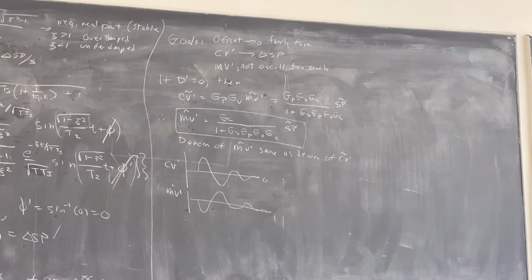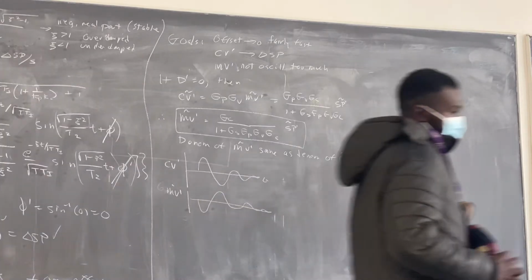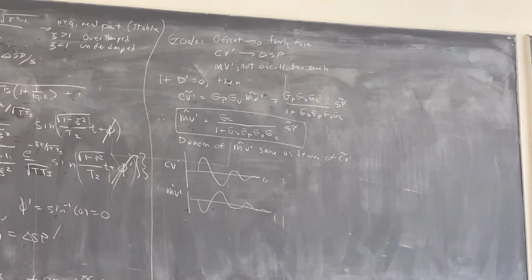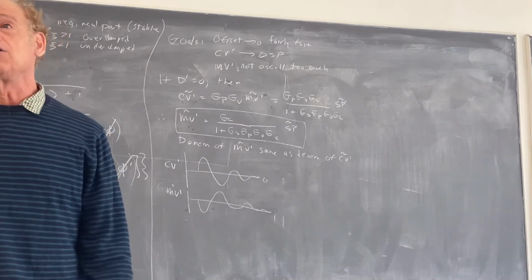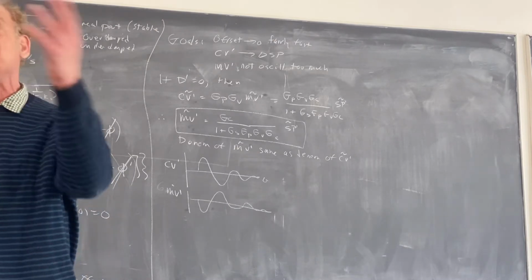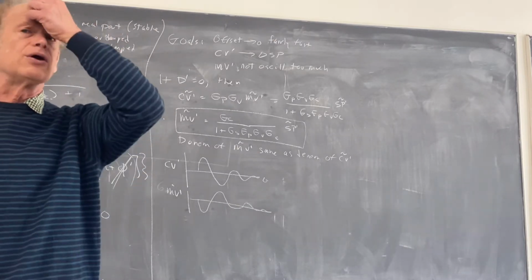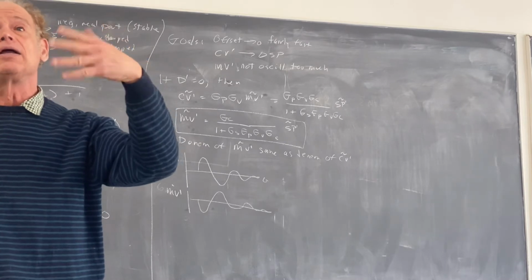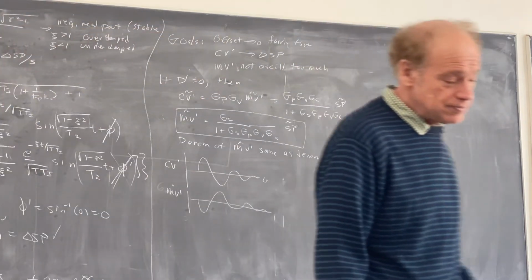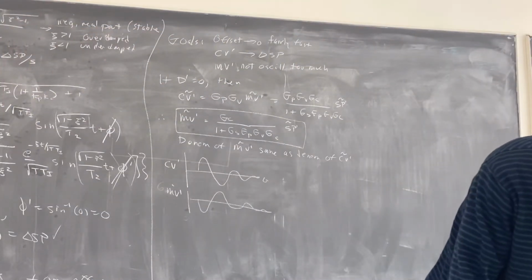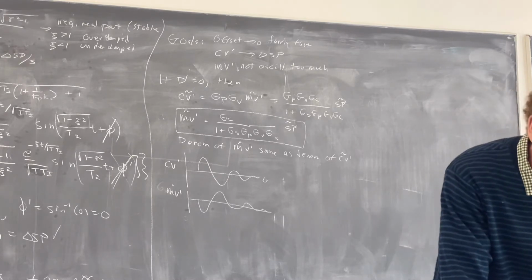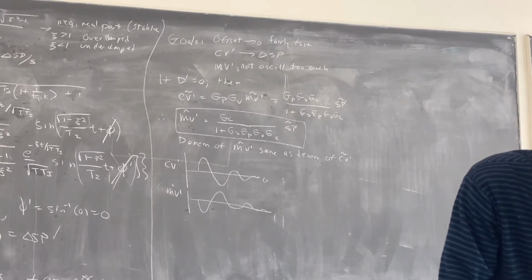And if you had an analytic expression for the IAE, you would try to solve those three equations simultaneously for the best value of Kc, Ti, and Td. If you could do that, usually your models are not that easy to solve. You don't have them analytically where you could, for IAE, take those derivatives. Although it's conceivably possible because you can solve nonlinear equations analytically today.